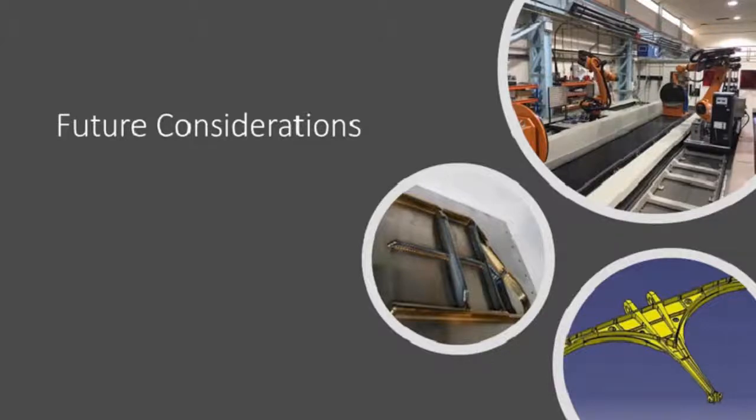Due to the differences in ALM compared to conventional manufacturing, the follow-up processes for a manufactured product's quality are different. In order to provide a basis for future certification activities for ALM technology, it is important to collect and analyze information related to established production steps for ALM parts, particularly when considering qualification and certification of primary and secondary aircraft parts, as ultimately this determines a product's quality.